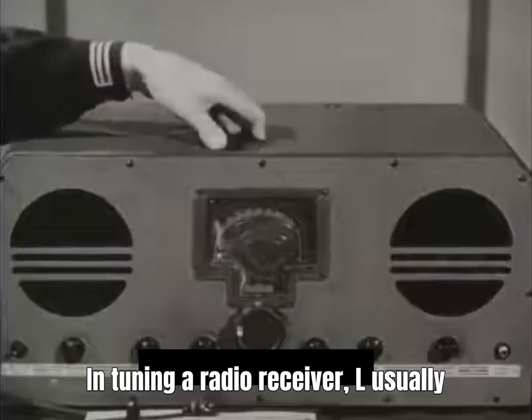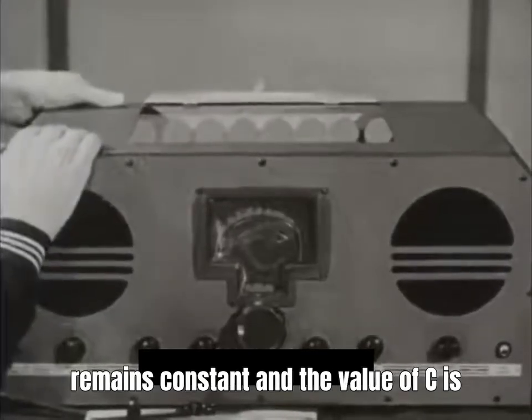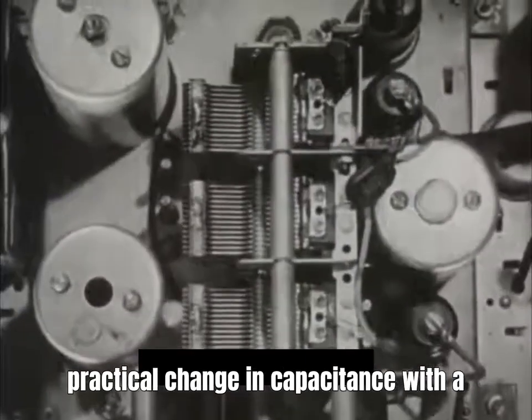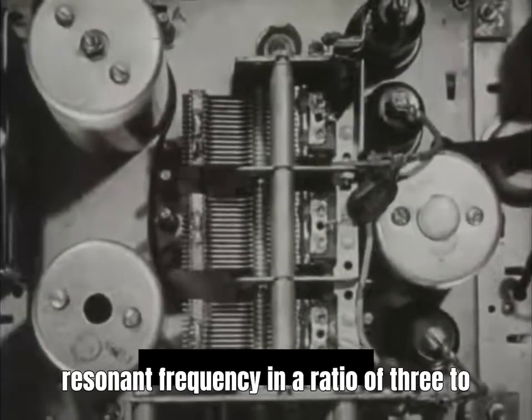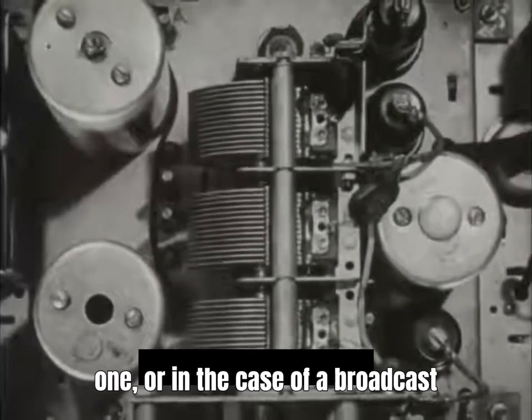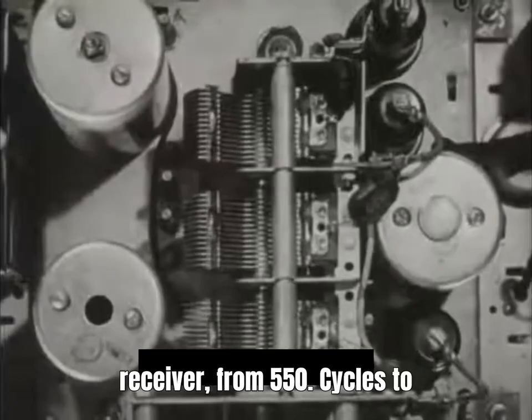In tuning a radio receiver, L usually remains constant, and the value of C is changed. In general, the maximum practical change in capacitance with a given inductance will allow a change in resonant frequency in a ratio of 3:1, or in the case of a broadcast receiver, from 550 kilocycles to 1500 kilocycles.